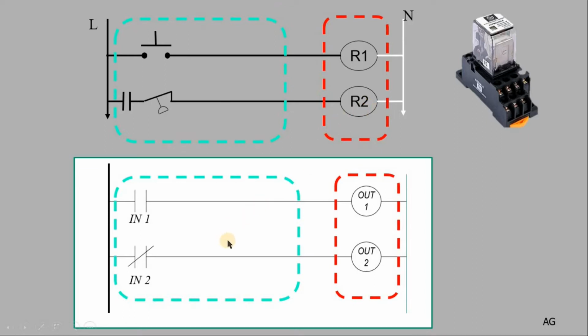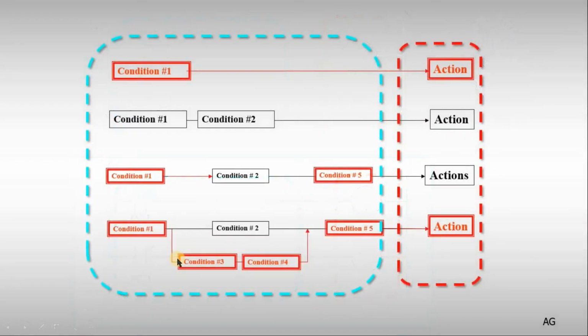In ladder logic, we follow the same concept or philosophy of having a power rail, and in the power rail what flows is the logic. Of course there is no power here, but the logic goes through a contact and goes through another contact until it reaches your output or your required action. Notice here we have a normally open contact and a normally closed contact. What does it mean? Because this is very important, I hope you concentrate on the next slide to understand what we mean by normally open contact and normally closed contact in ladder logic.